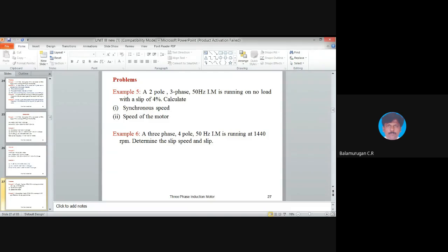The magnitude is 1.5 phi m at 0 degree, and at 60 degree also we get 1.5 phi m. If we calculate for any degree, the magnitude of the flux will be 1.5 phi m only, but the angle will be continuously changing. Suppose this is 30 degree, it moves to 60 degree for the next instant.